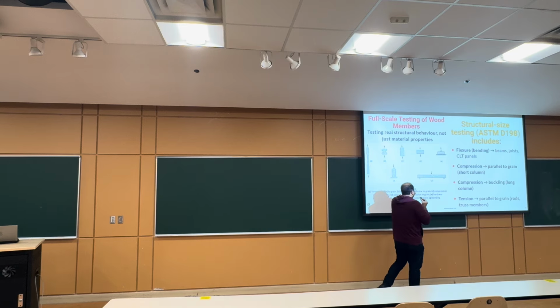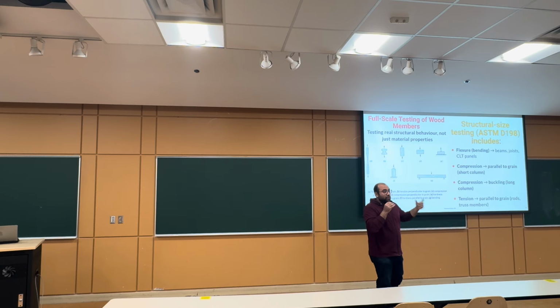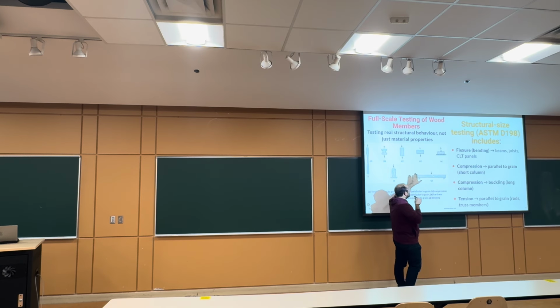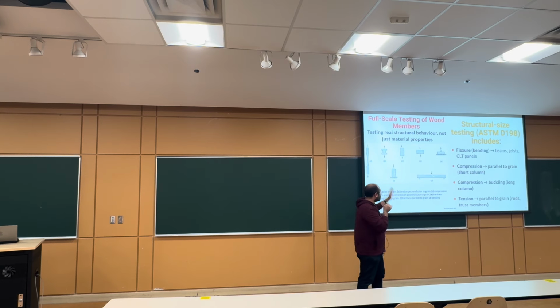In bending, it's a bit hard to apply the bending in or against the grain direction, because bending requires a longer specimen. So we just have one orientation for bending. This is the orientation for the static bending test. As we can see, we have two supports, and the load is applied in the mid cross-section.